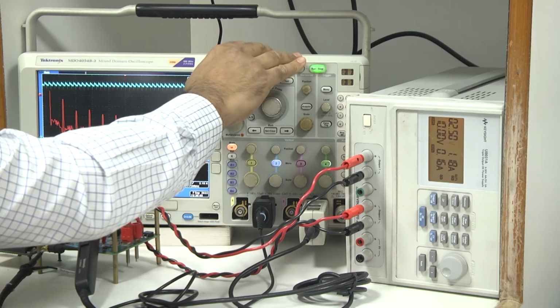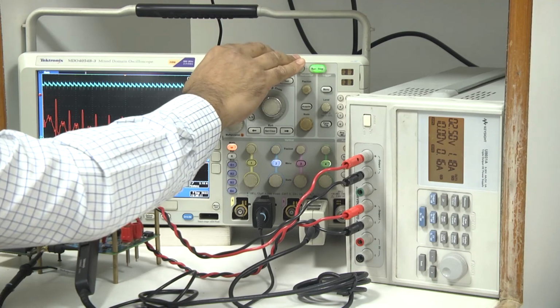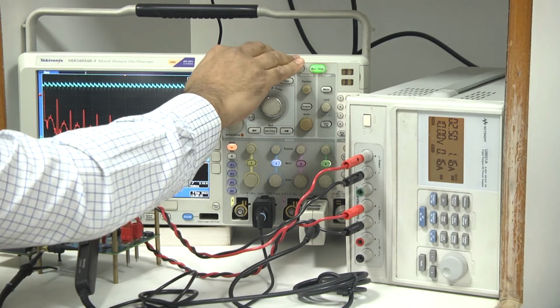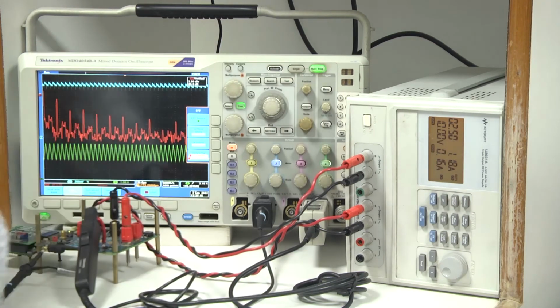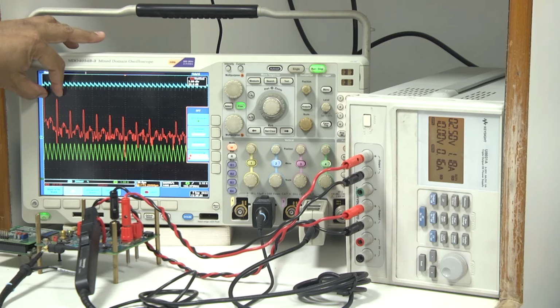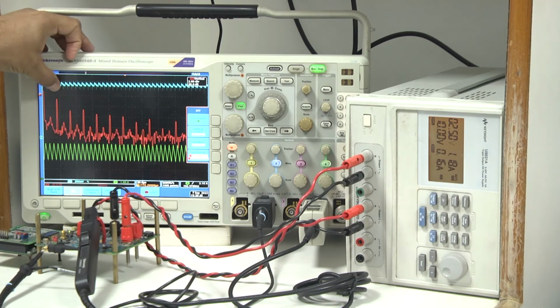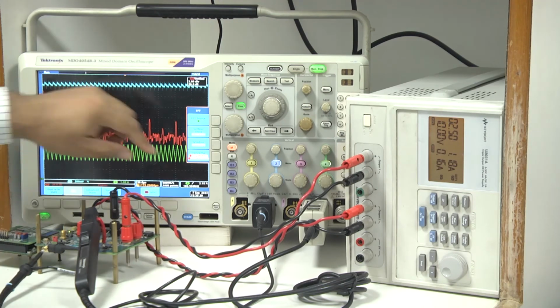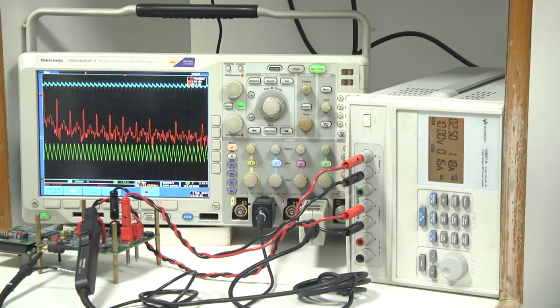So, this is the 0 frequency coming. Now we have placed the 0 frequency here. You can see there is a spectral peak at 200 kilohertz, because this length is 250 kilohertz and this one is 200 kilohertz. That is our switching frequency, that is the fundamental component, and then there are harmonics.